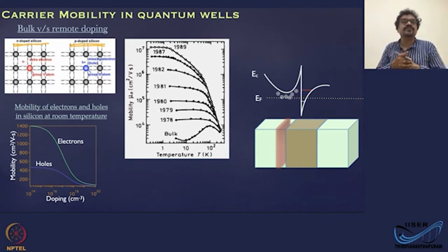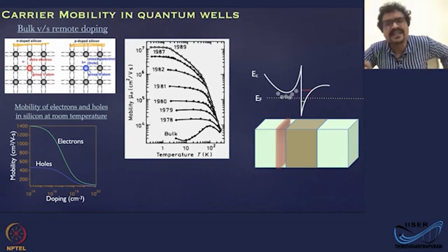Then the observation of quantum phenomena at any reasonable size scale is almost impossible. On the other hand, if you put far fewer impurities, then of course you can get a higher mobility. But again, mobility is also controlled by phonon scattering. So you have to go to low temperature, but at low temperature you have far less carrier concentration, because these carriers need to come from the valence band, or the conduction band for N-type. Then what that means is you have absolutely no conductivity, it will freeze. You will not have any carriers. So it's actually a very tricky situation.